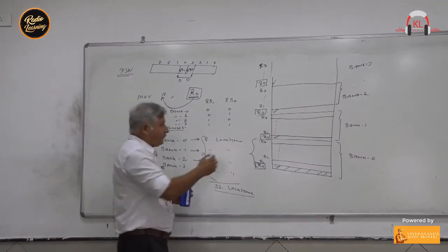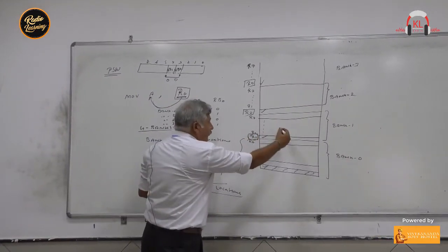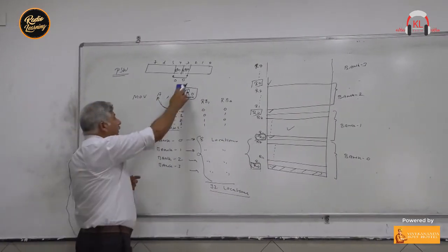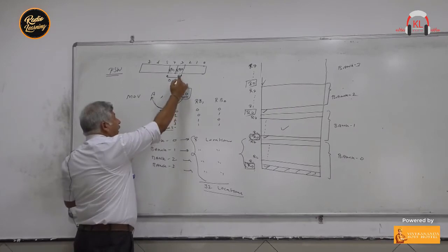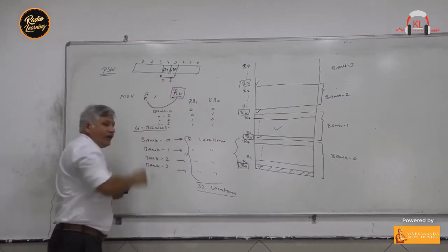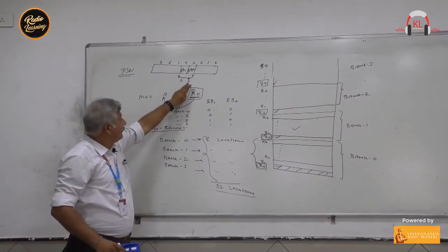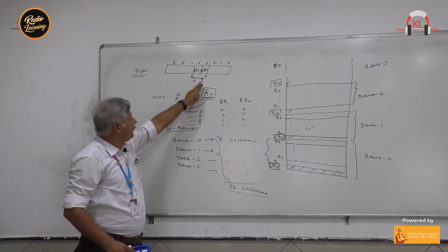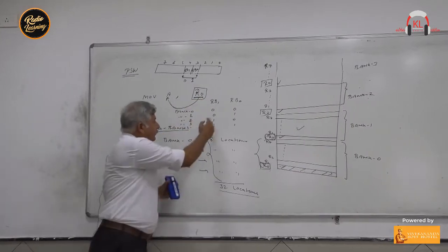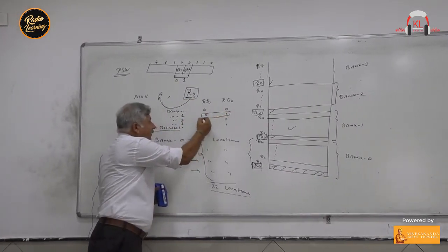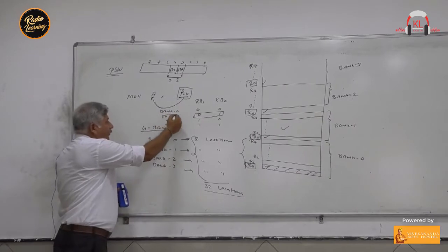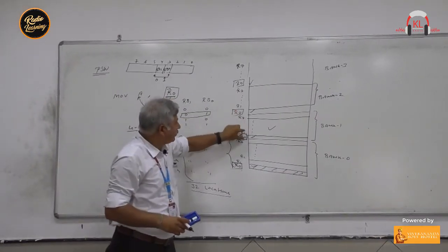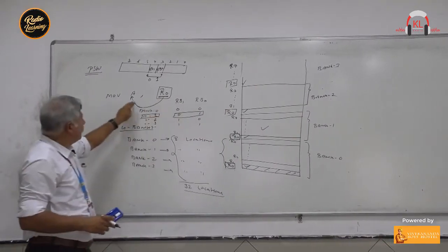And if we want the content from R0 of bank number 1 to be transferred to the A register, then we have to make RB0 1. If we make RB0 1, then what will happen? RB1 is 0, RB0 is 1. In this case, our bank number 1 will be selected. So the value from R0 of bank 1 will be transferred to A.